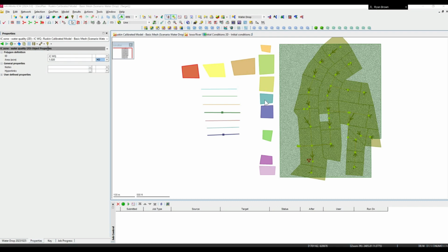Next up, we do have mesh level zones and mesh zones. These are pretty similar to each other. I'm going to start out with mesh zones here, though. The primary piece of this would be to override 2D zone minimum element area, so you can add in finer detail or coarser detail into certain areas.